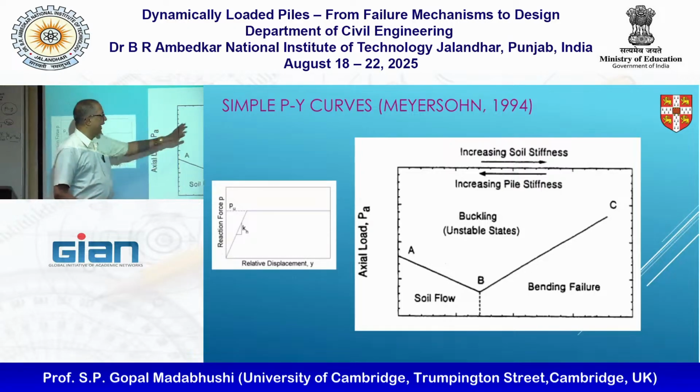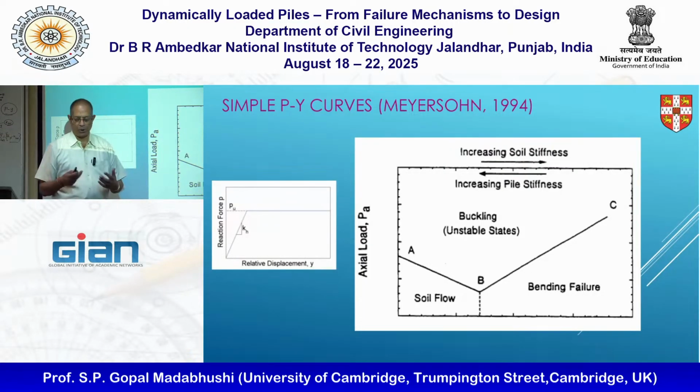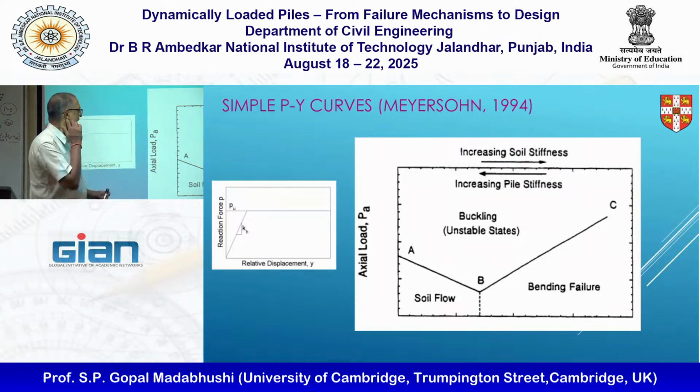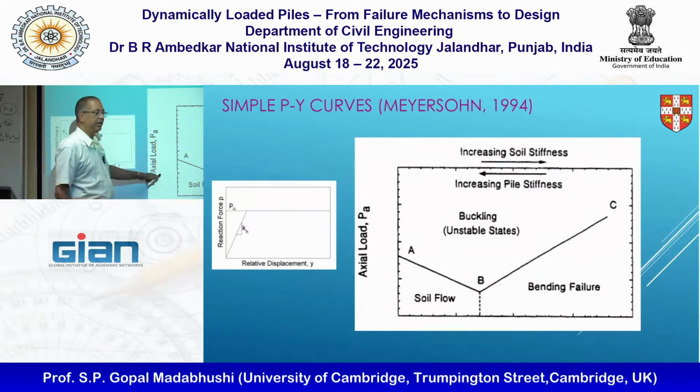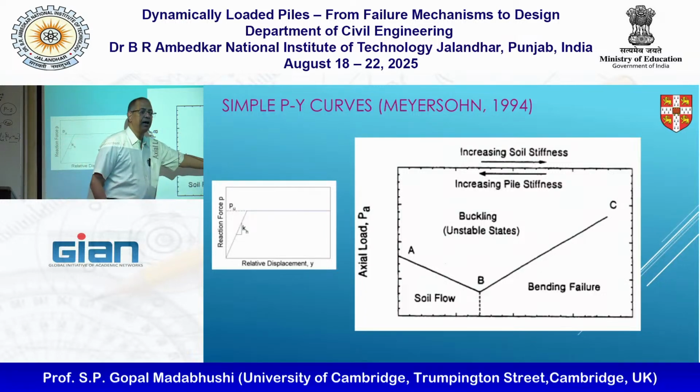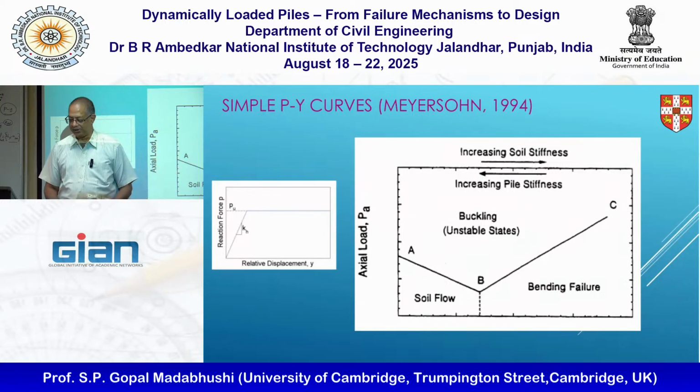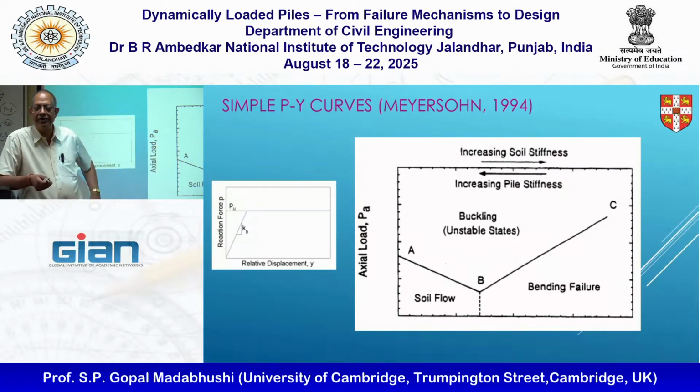So this is a neat framework to show. All I really need to know is what is my axial load, what is my soil stiffness and pile stiffness, and I can then predict how my pile is going to behave, or how it is likely to fail. You like this? Everything we learned, we are putting together into one unified state.